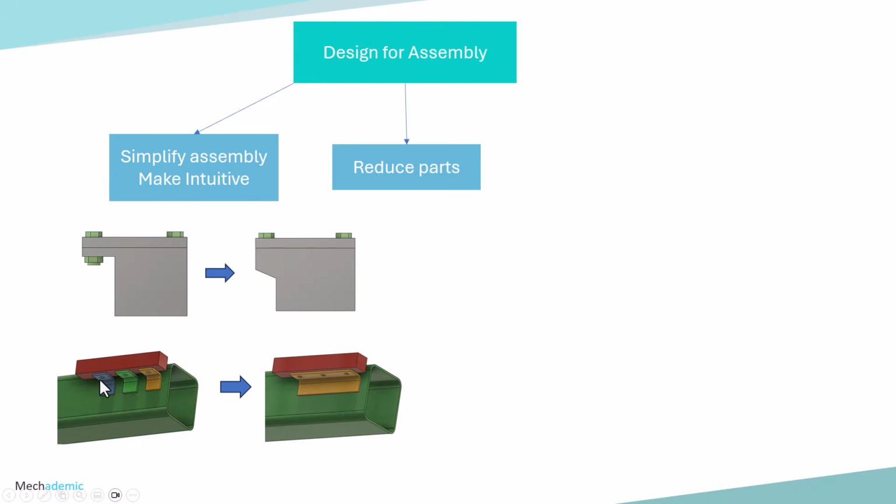We can imagine that welding these 3 brackets separately will almost always not maintain the top level of the mounting surface. It will not be uniform, because when we are welding there will be variations, whereas over here it will have a uniform mounting surface. Hence the overall performance also will be improved, the precision will be better, and the assembly process is simpler,